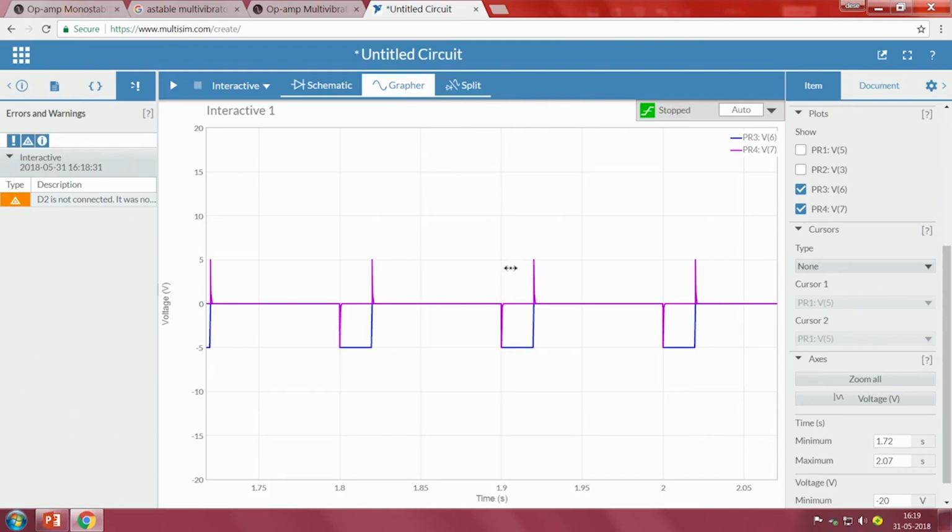It should happen only when the capacitor is discharged, or the capacitor voltage is lesser than minus 7.5, or lesser than minus VCC value, minus the lower threshold value. So, in order for that to happen, this particular spike we should not pass through the system. How can we do that?